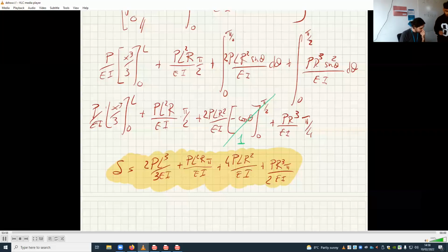Okay. For the maximum one, it said take into account factor of safety. Yes. And I posted a video from week 1, the YouTube. I watched a video on how he found this, and this is how he did it. So he drew this graph, and he said that tau max should be P over 2. Tau yield is sigma yield over 2. That's fine.